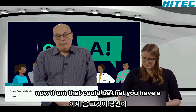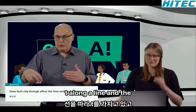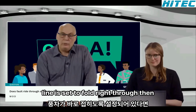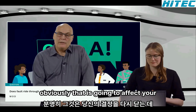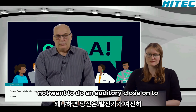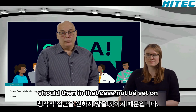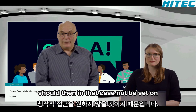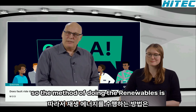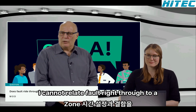Now, it could be that you have a T along a line and the generator or windmill feeding as a T onto a line is set to fault ride through. Then obviously that is going to affect your auto reclosure decision, because you would not want to do an auto reclosure onto a generator still connected to a faulted line. And fault ride through should then in that case not be set on. It should be set to separate during a fault. So the method of doing the renewables is a different subject. But other than that, I cannot relate fault ride through to a zone time setting.